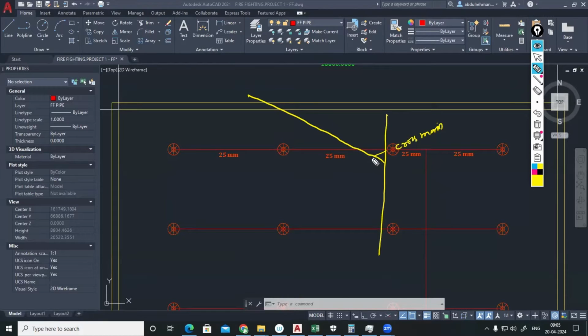With respect to the zone only we can do. Here, to address the flow rate, we will have a ZCV, zonal control valve assembly. And now the cross main will take a vertical pipe, a 100 mm nipple will be taken there. Then from there we will take branches. These are called the branch lines.